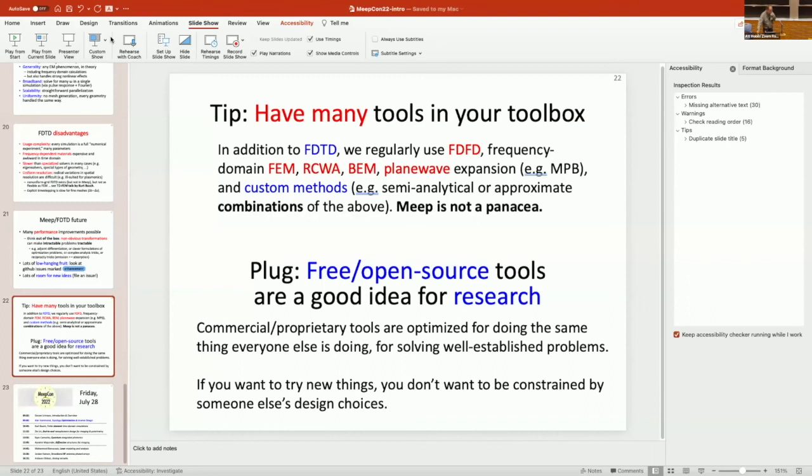Yeah, so definitely when you're developing numerical solvers, you need to validate them. You need to make sure they're correct, and you need to make sure that they're converging at the expected rate, right? Often a source of bugs is that things converge, but converge more slowly than they're supposed to, which is an indication of bugs. And here, the whole purpose of the tool is to solve things you can't solve by hand. So then how do you check it?